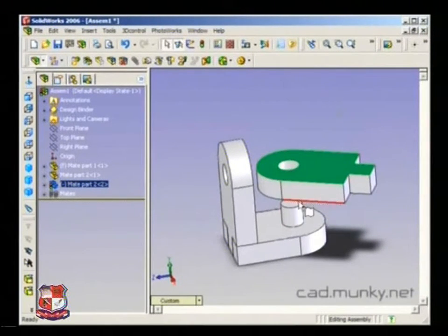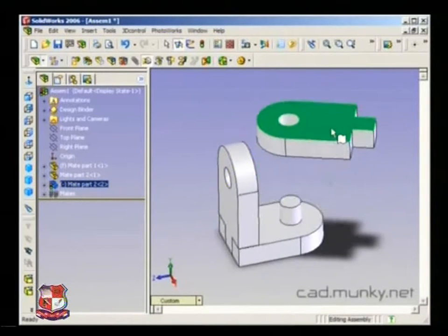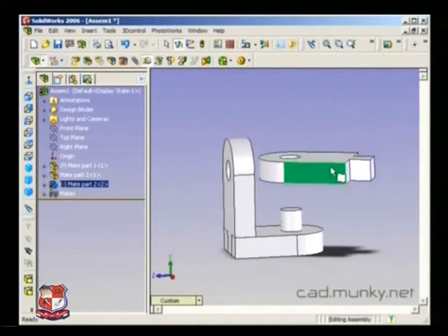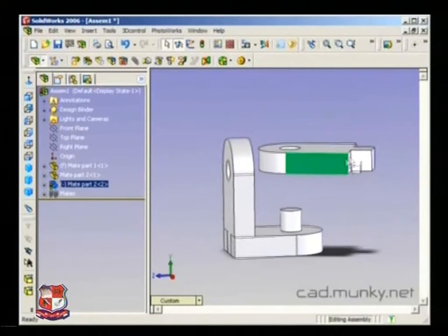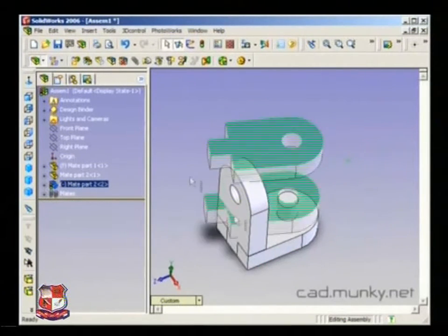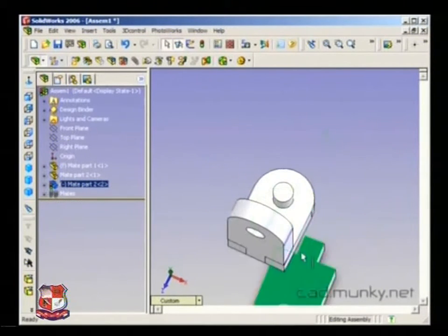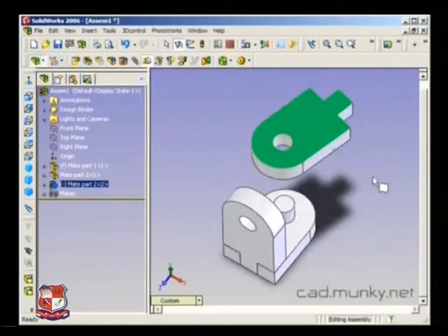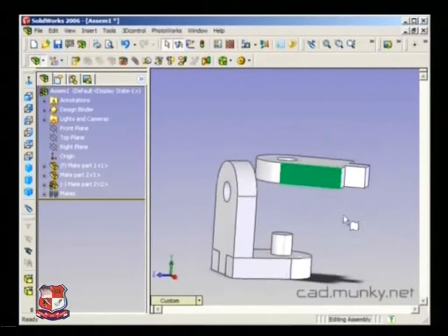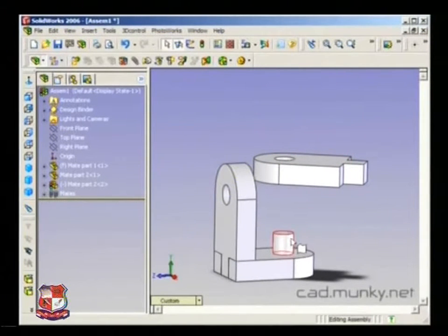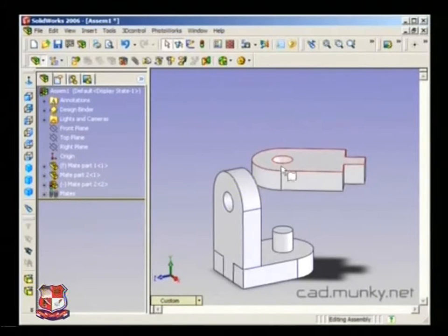Now you can see that these inside and outside faces are lined up in a way that the pieces have to be right on top of each other, and the freely moving piece that's not fixed in place can be rotated like this. I've also got this motion up and down because it's not taking into account the fact that the peg stops here. It's extending that cylindrical surface infinitely up and down. Same with the inside surface here.